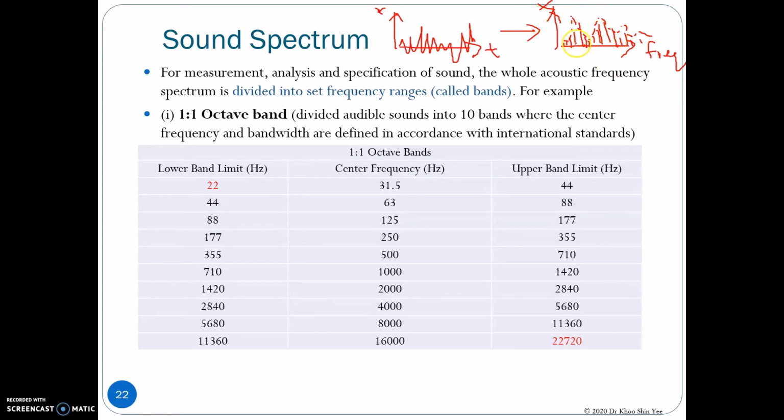For vibration analysis, we prefer to have a very small delta f, which represents a very high resolution for our frequency domain. However, for sound analysis, the approach is different. Instead of discrete frequency data, in the sound spectrum we have frequency bands, where we group the sound data into several frequency ranges, which are called bands.